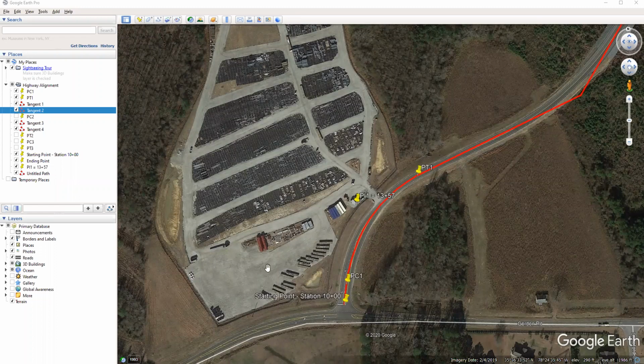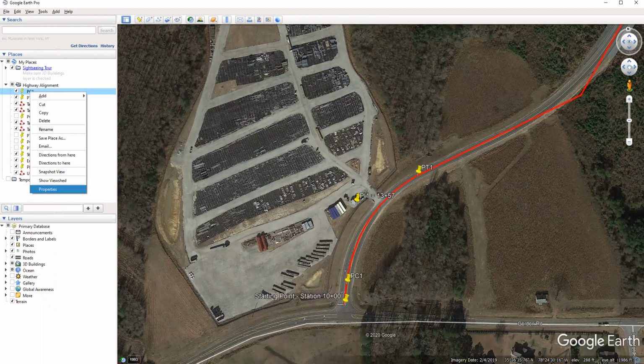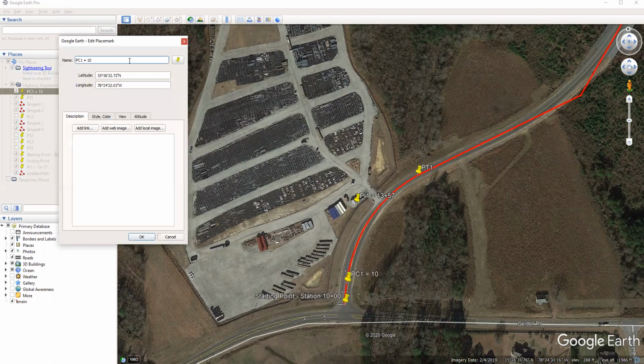For this, I'm just using round numbers. We can be more precise if we were actually designing this road. I just want to illustrate these distances. And so that gives us a PC station of 10 plus 79. So we got that from starting at the PI, 13 plus 57, and subtracting off the tangent length of 278.